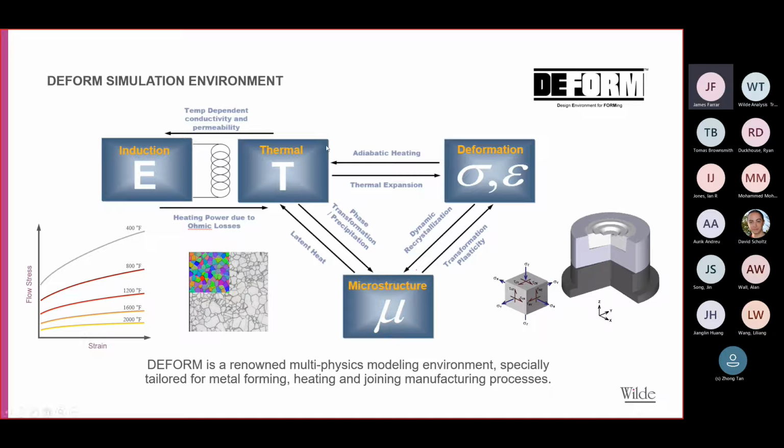And in terms of heating your part up, we can look at that either through sort of furnace modeling, or induction heating, or resistance heating applications. And what we're really interested in is understanding the flow of the material by evaluating the flow stress throughout the process as the strain evolves, for different strain and strain rates and different temperatures. And that's the crux of what we're trying to solve in DEFORM.